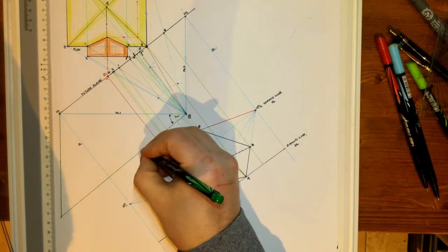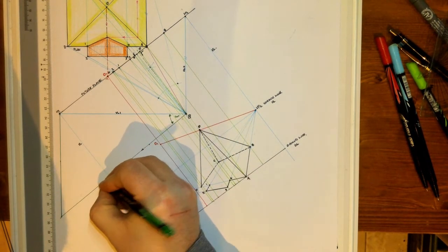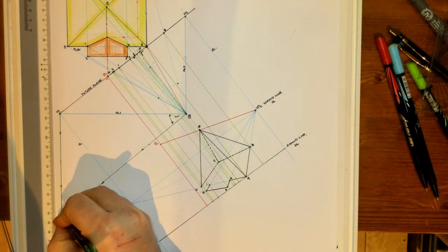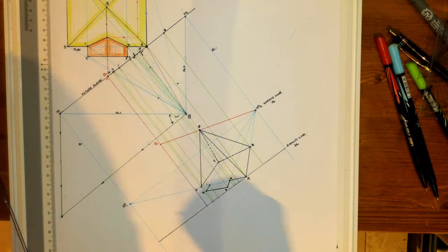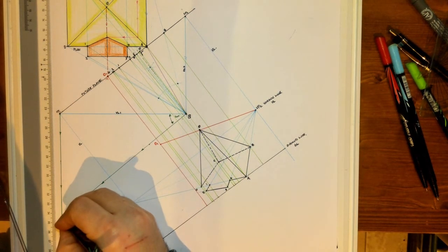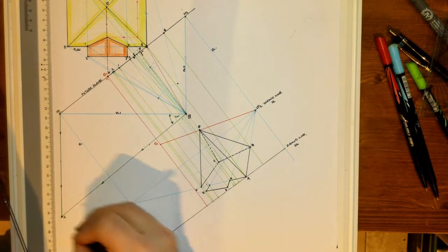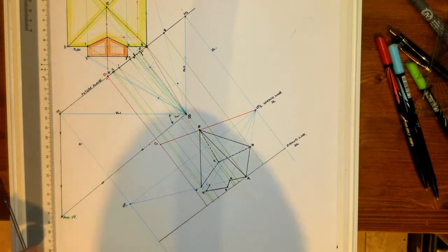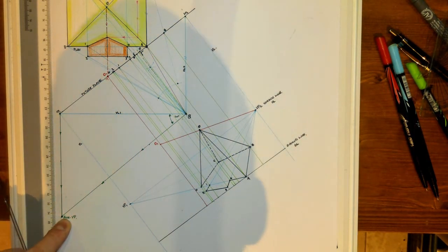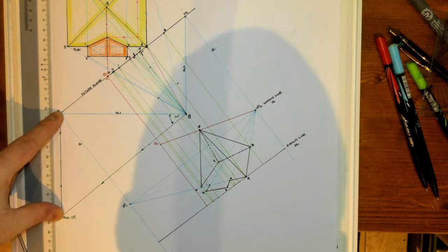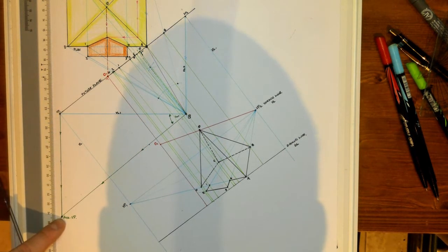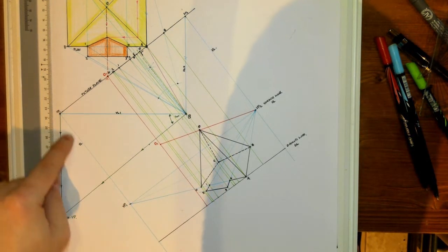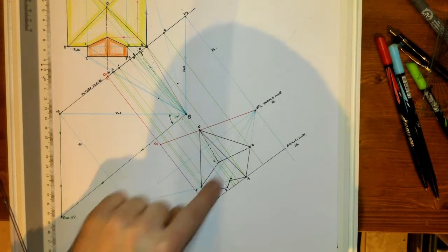Okay, so we might just use a set of arrows to indicate this, and to indicate that this one travelled down like so. And what that gives me, we're going to call this distance Aux VP, A-U-X VP. Now, we're not going to use it from that position. What we do is we take the length of this line, from VP1 to Aux VP. We're taking that length and we are now going to position it above VP1 here in our auxiliary elevation. Remember, this is an elevation.